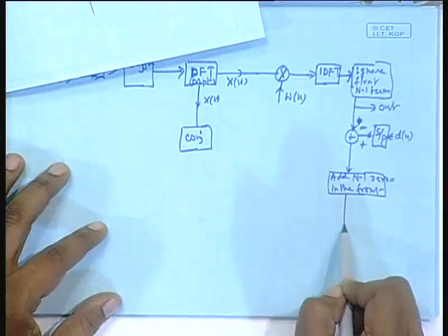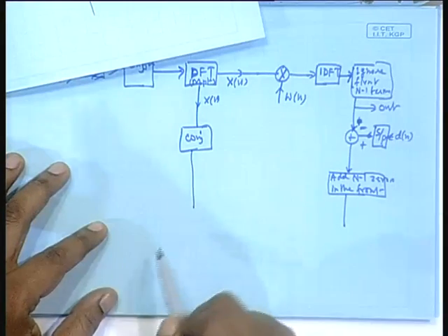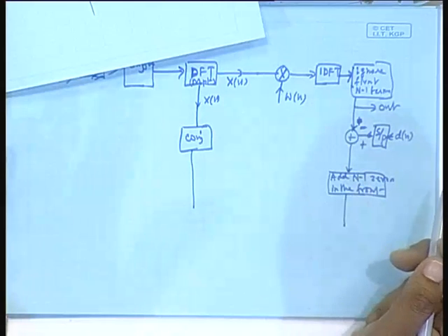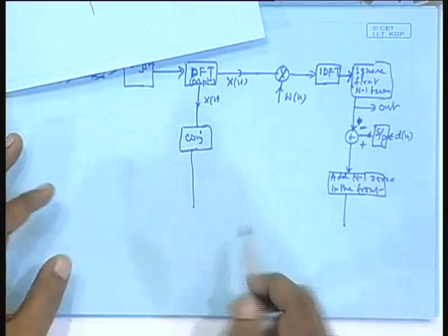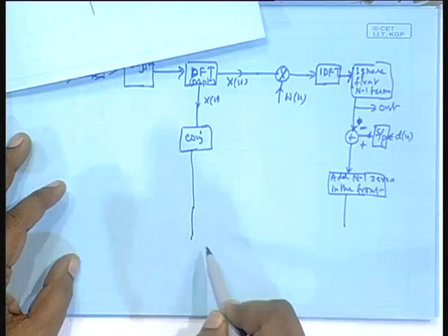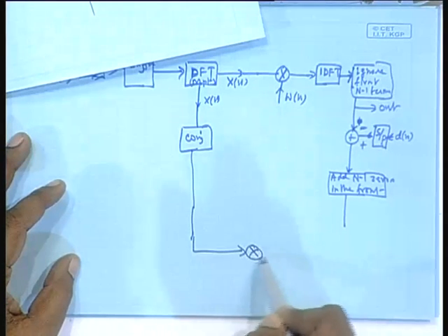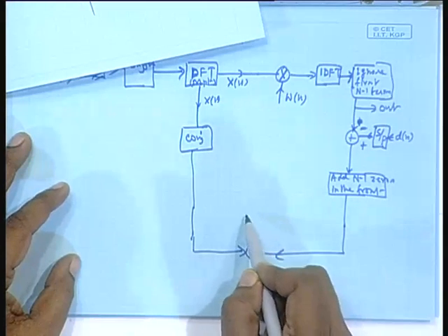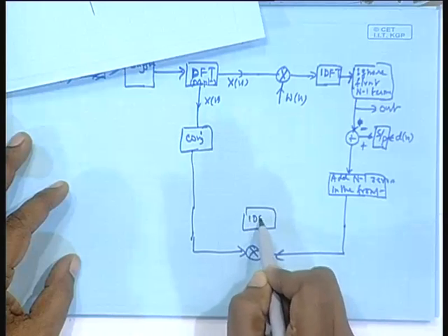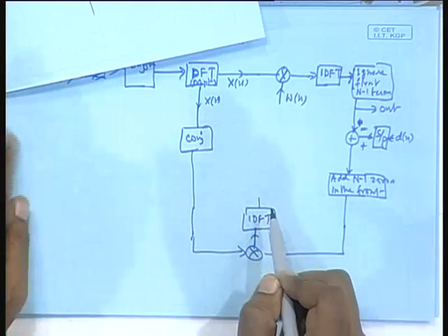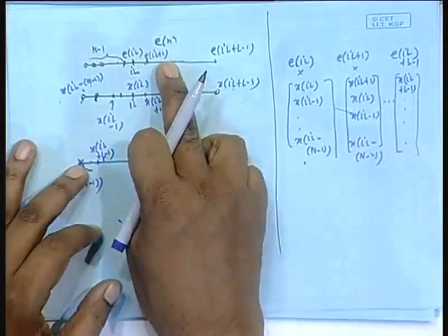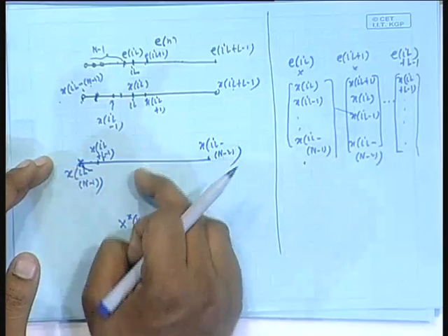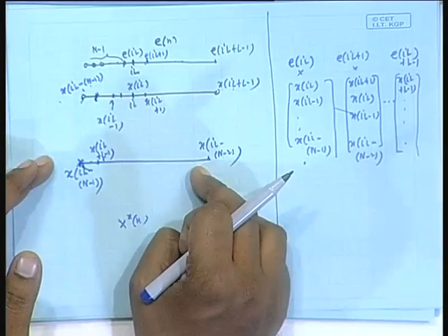Now, you take the DFT of that, the two DFTs are to be multiplied. There will be a multiplication by mu also somewhere. Okay, mu I will do later. Two things multiplied and then IDFT. So, by IDFT, what do you get? Circular convolution between the two. But I told you between the two, I will return only the first n ones, remaining ones I will put zeros. Why 0? You will see.